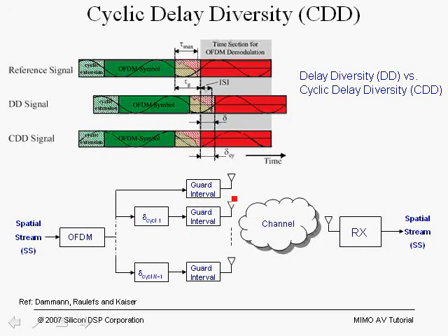And for N transmit antennas, we add different cyclic delays for each different transmit chain. Now let's take the case where we're considering cyclic delay with two chains. As the signal is transmitted through the channel, it is received by the receiver through different multipaths.